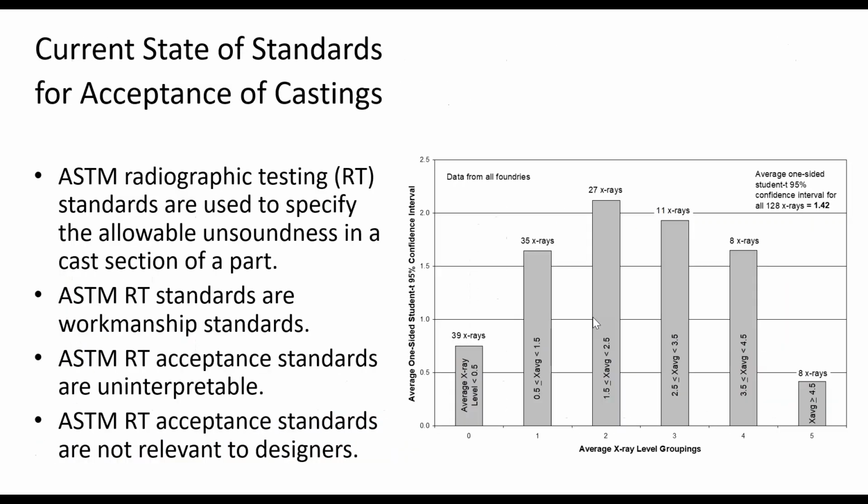We even found that the best, highest level NDT person doing the same material twice, 128 x-rays of a flat plate, so there's no features to screw him up, and he could see the surface, actually only agreed with himself about 40 or 50% of the time. So really that 50% probability of agreement is fairly common. It's common in lung x-rays too, by the way, for tumors and for TSA catching people trying to get guns in.